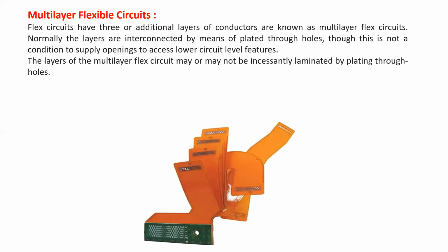The next type of flexible circuit is referred to as multi-layer. It has three or more layers of conductors on the PCB. Normally, the layers are interconnected by means of plated through holes. Through this, it is not necessary to supply openings to access the lower circuit level features. The layers of this multi-layer flex circuit may or may not be laminated together. This is the picture in which we can observe the multi-layer PCB.